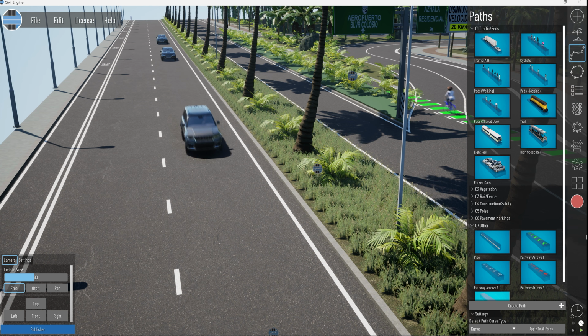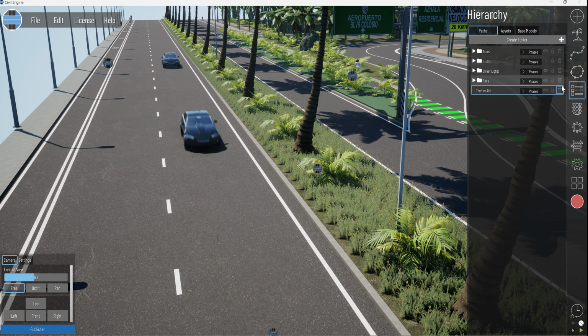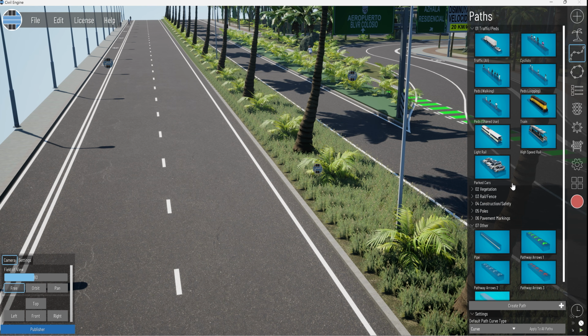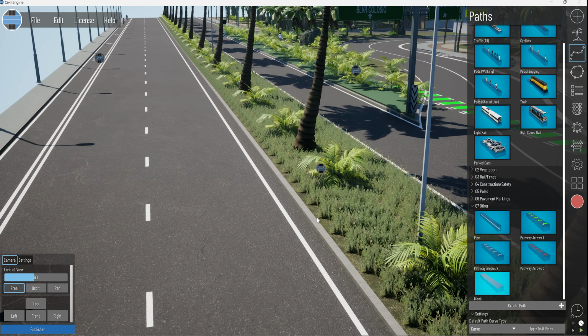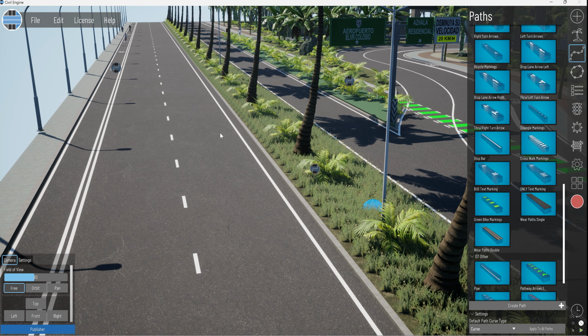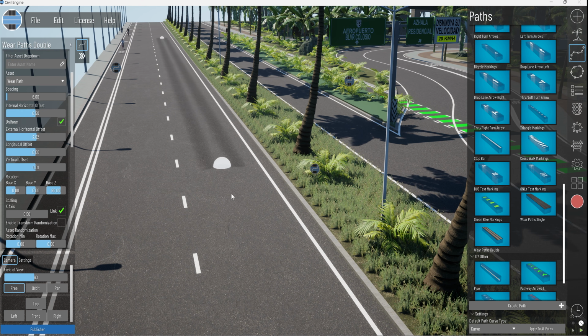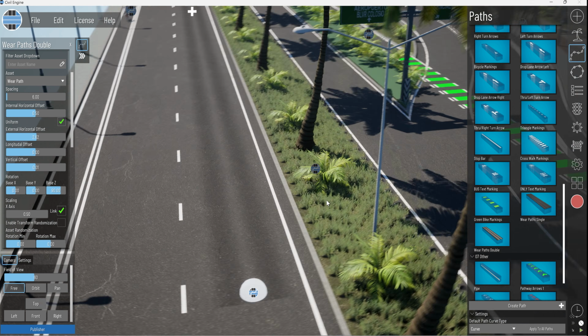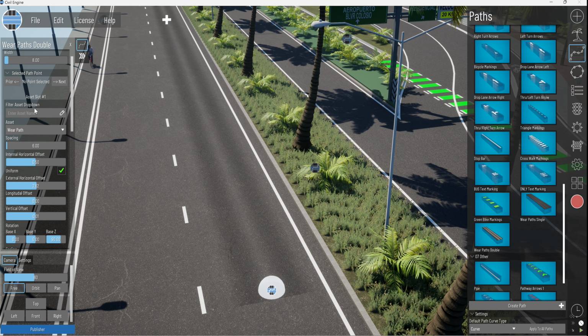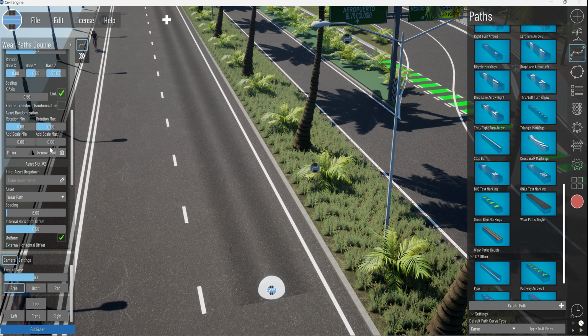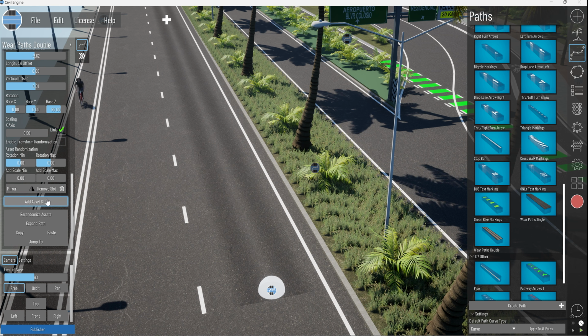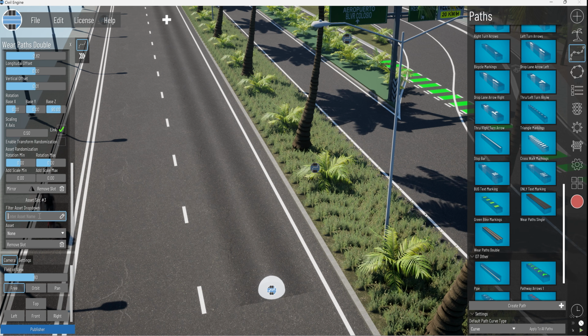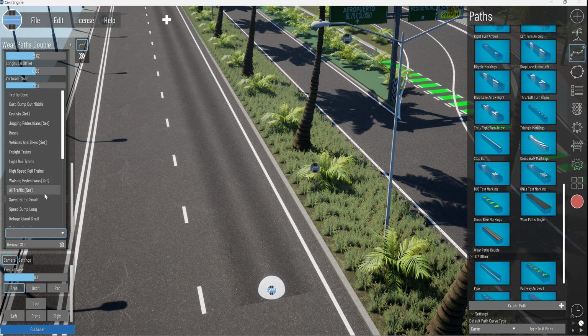If you do still like the double wear path, that's also an option. If you go to our path presets, you can go to pavement markings and use wear paths double, and you can still get that. Those don't have traffic assigned to them, but you could add traffic to that either directly as part of this path, or you could place another path. If you wanted to add it directly to this path, then you just go down to the bottom, add an asset slot, and you want to search traffic. That will filter your drop-down list and do all traffic set.